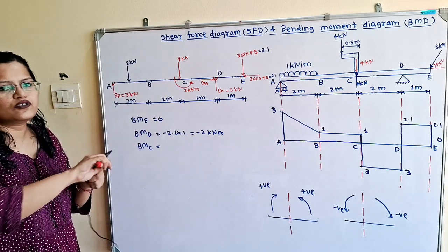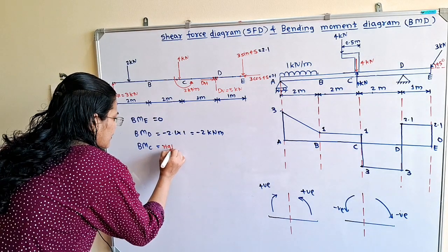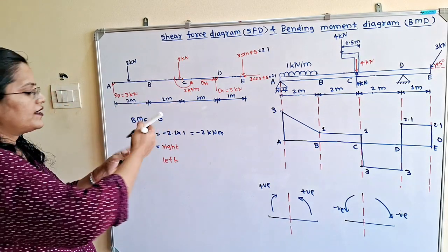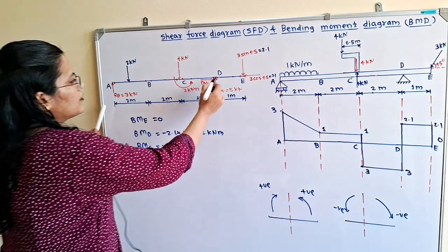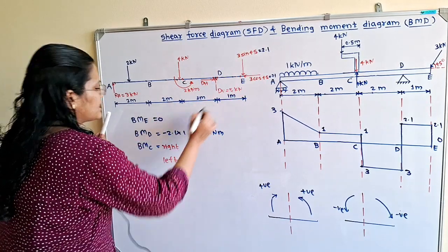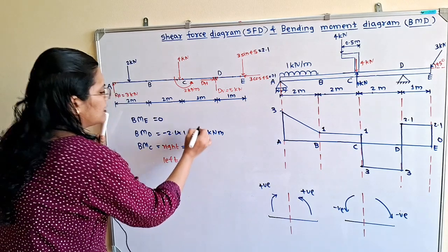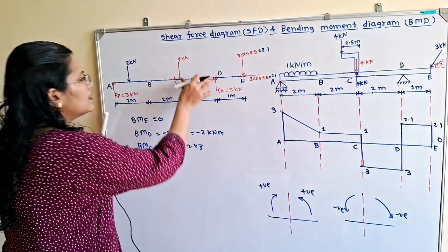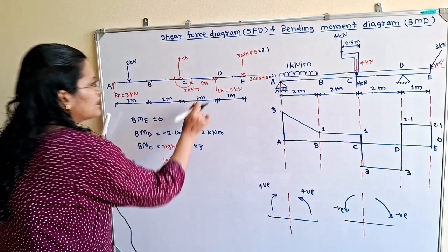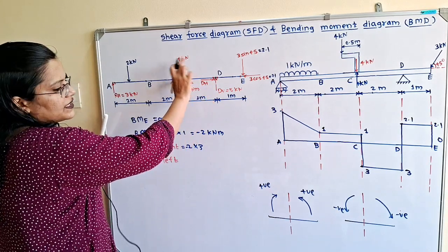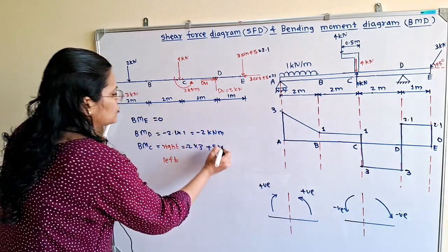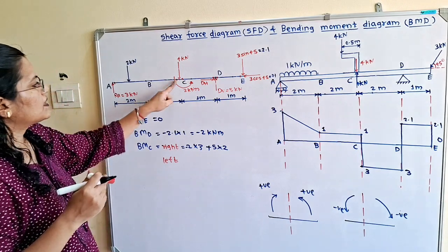So we will select here the 2 points, right and left. If I take the immediate right hand side point, then at the right hand side point we have to take these two loads, that is 2.1 multiplied by this distance 3. If I move the compass, there is clockwise direction, so with minus sign. Then again for this dV there is the anti-clockwise direction, so use plus sign, 5 multiplied by this distance 2. Now we will consider the left hand side point.